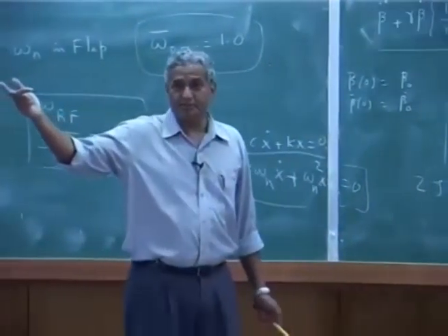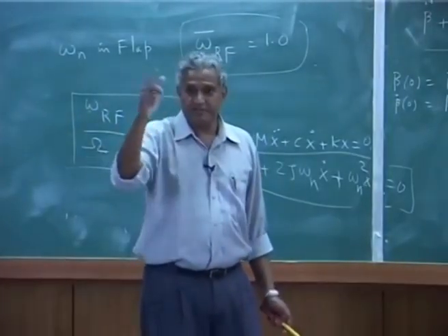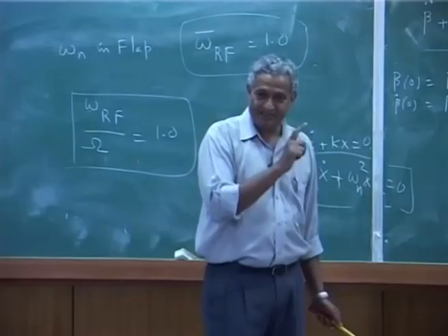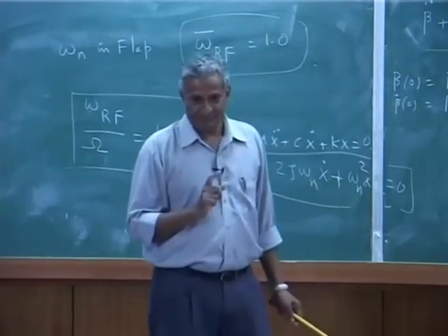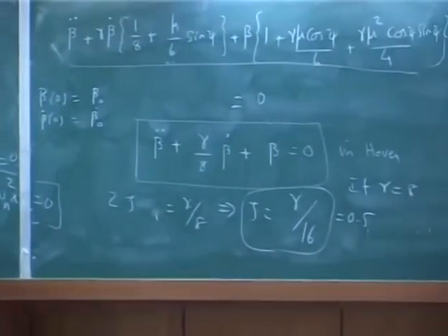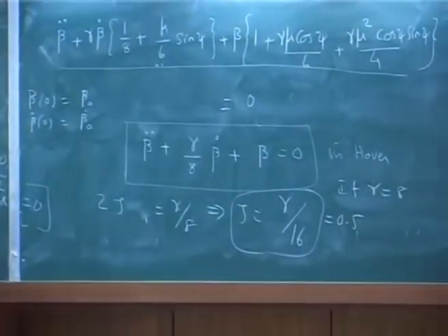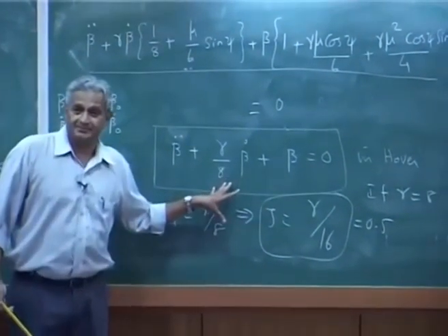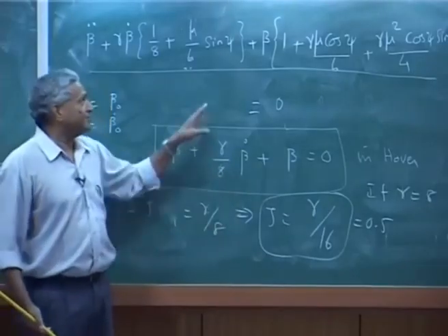Gamma is aerodynamics. Suppose you rotate in vacuum, there is no damping, because it depends on rho, the density of air, and the lift curve slope. They contribute. Now, this is a heavily damped system in hover, in the sense when mu is 0.